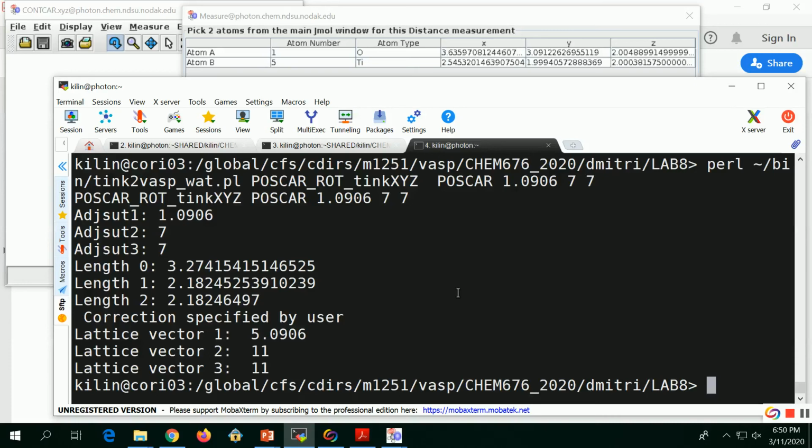Good. So this vacuum, go ahead. You want to define that maybe to help them to be in a reactive field. When this vacuum space becomes larger, it's hard for the replicas to react with each other. They stop interacting. Right. If they are close, they can electrostatically attract or repel, and orbitals can hybridize. Exactly. And we do not want this. The bigger the vacuum, the better for correctness of results, but the smaller, the better for quick calculations.